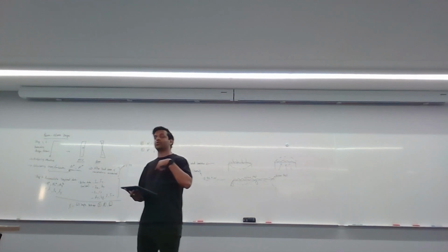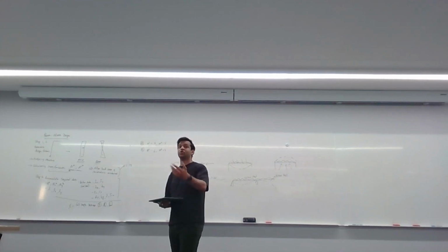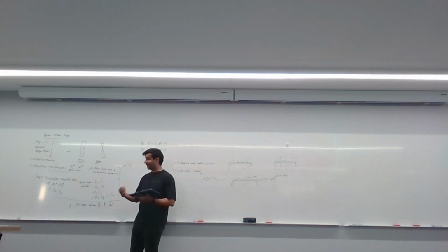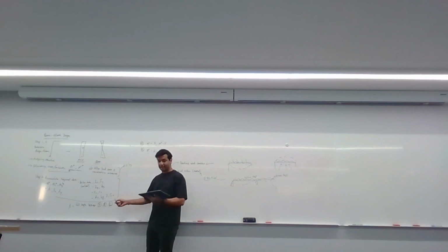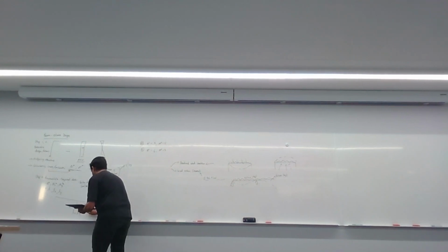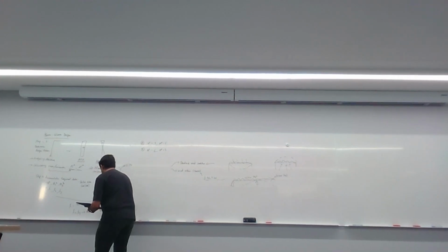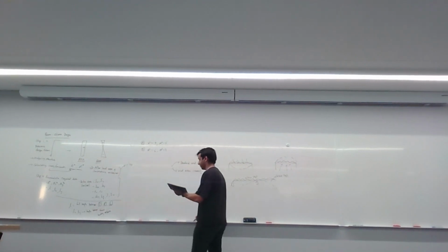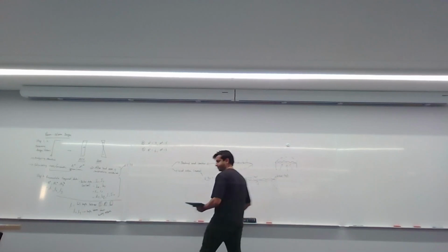Okay. So remember, short of them actually telling you what it is, sometimes it might be shown and you need to figure it out. So remember, the length here that you need to calculate is the full length between F, P, and L. And Lx and Ly are the length between your column buckling restraints. Okay, this is really important.